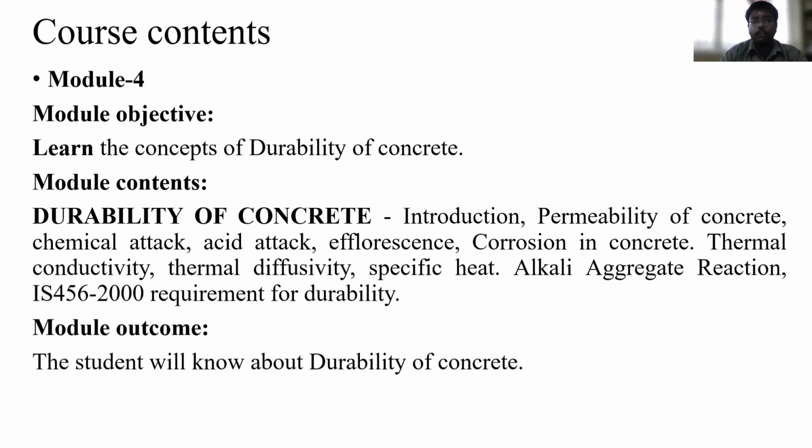In the durability module we are studying the introduction of durability and permeability of concrete, chemical attack on concrete structures, acid attack on concrete structures, efflorescence, and corrosion of reinforcement bars in the concrete, and thermal conductivity, thermal diffusivity or specific heat, and alkali aggregate reaction. Alkali aggregate reaction is the most important concept, where the alkali content in the cement, which is a binding material, reacts with the aggregates, and some additional compounds form which obviously affect the properties of concrete. That is studied under the heading of alkali aggregate reaction.